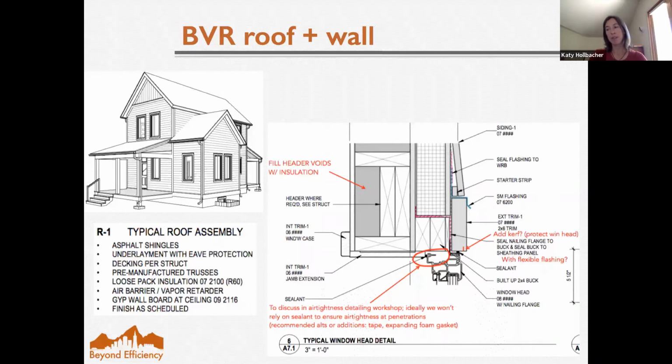What we've found in our projects is once we've landed on a good building envelope, whether it's passive house level or it's pretty good house or whatever kind of reference you might want to use, we generally find that ventilation becomes the dominant contributor to heating related energy use. And if you then reduce that aspect by 80% because you have heat recovery, you're suddenly dropping the heating component of your building's energy. You're reducing it by 70 to 80% when you look at a really good building envelope combined with heat recovery ventilation.